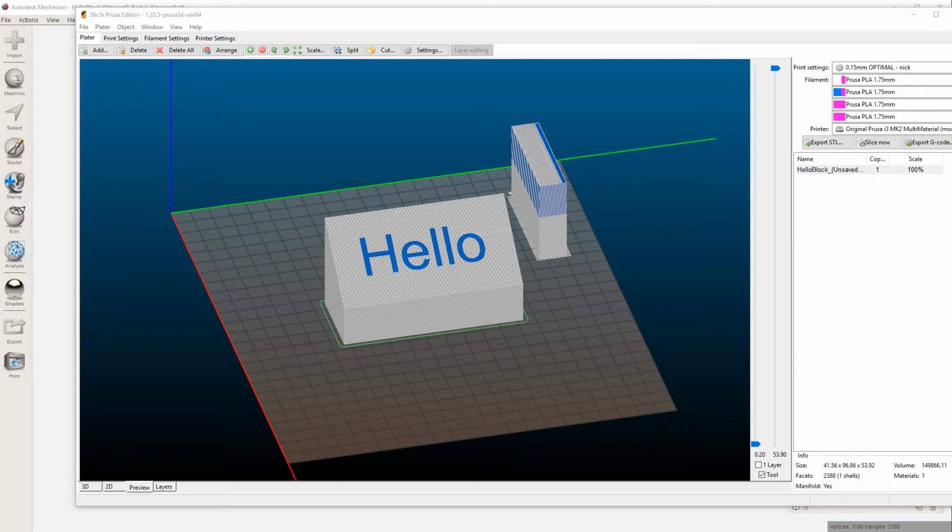I have another one here, you can see some hairiness on the sides, because this is soluble support material. This is from that print that I did of the broken tibia, where this is white material, and then it goes down to soluble support material. So this is actually pretty loose. If I were to put this in water, all of the soluble support material would eventually just dissolve away, which is pretty darn cool. That is how you do multi-material printing.